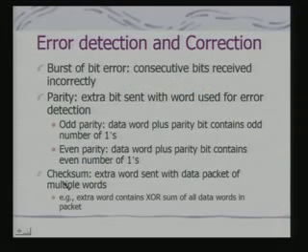Checksum can be generated using a variety of algorithms. It is an extra word sent with a data packet of multiple words. That word indicates whether the data packet that you have received is correct or not. The receiver uses the data part of the packet to recalculate the checksum and matches it with the checksum byte which has been transmitted.